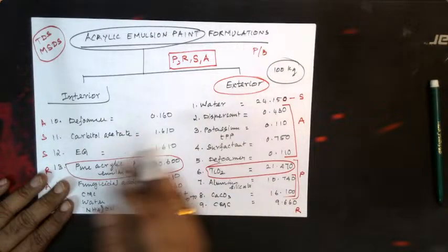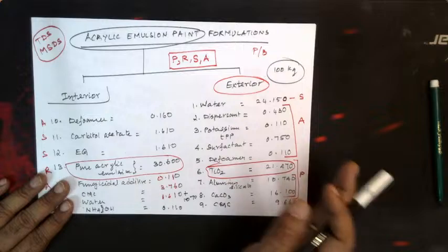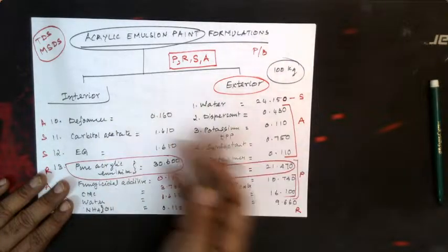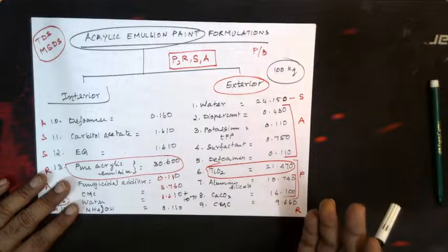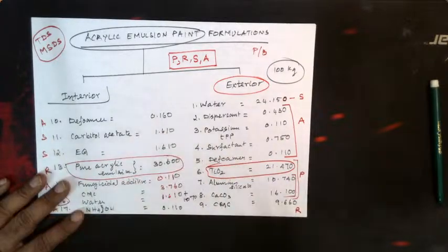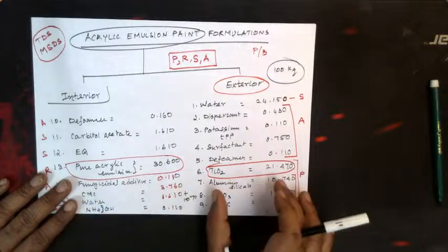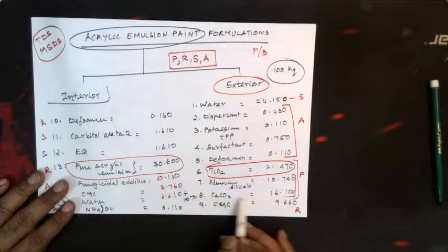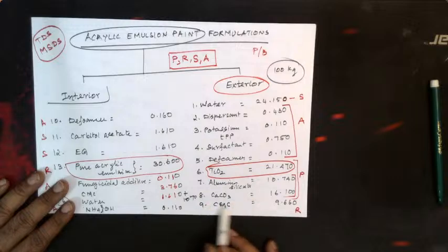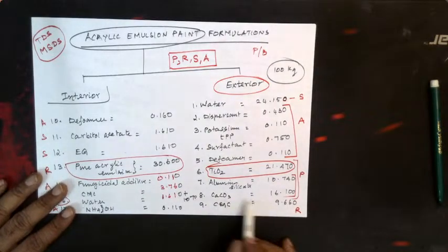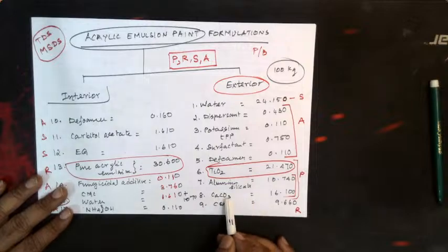Rutile is costlier than anatase. Apart from that, you have other pseudo titanium dioxide like monazite sand, or what you call UTOX, etc. Okay, but the original is titanium dioxide, and along with that we can add aluminum silicate, calcium carbonate. So these are all extenders, and particularly calcite is an extender, a filler, right?